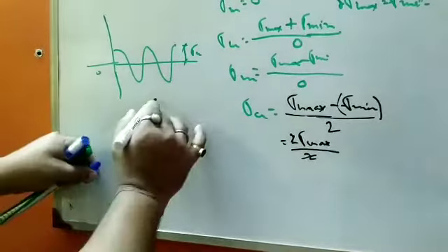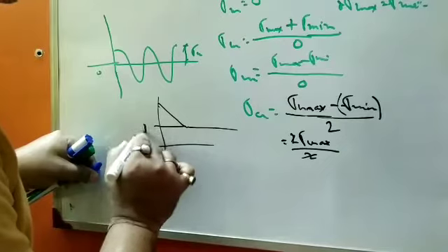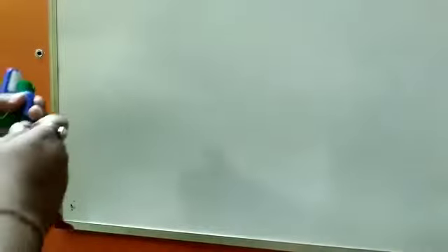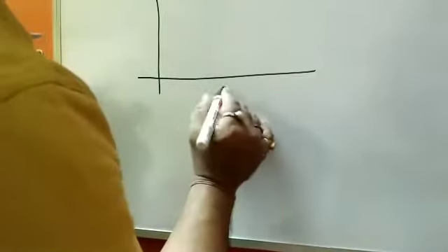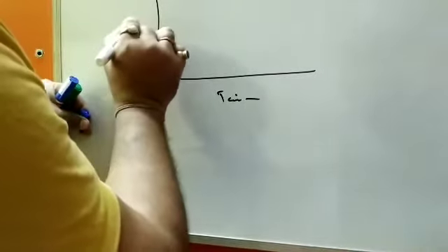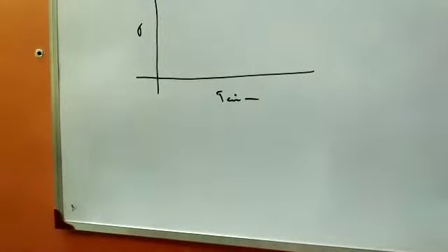Then for that we have gone for the SN curve. If you remember, we have the SN curve, and we found the endurance strength of the material. That has been discussed previously. Now, there are certain cases of loading where we get both components, sigma M and sigma A. If I plot the value of time over here, and plot the value of sigma, there are certain types of loadings which look like this.